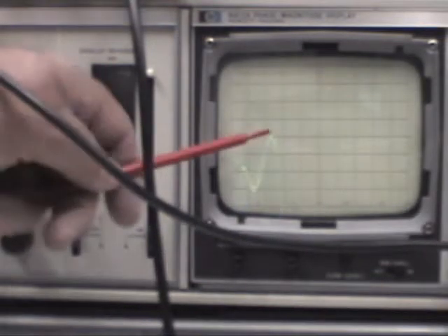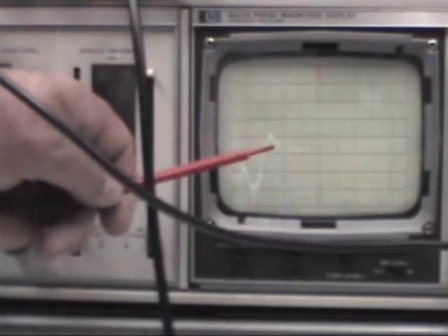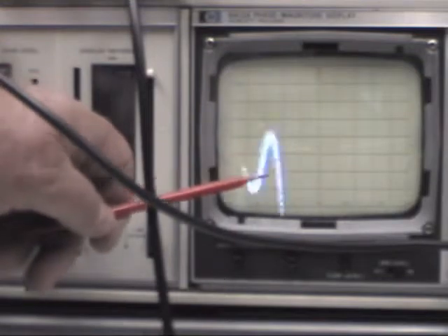And I bring it back down to the center if I can. Which I can't get it right back down to the center. But basically, what we have here is -1 dB right at that point right there. And remember these are 1/4 dB per division, 1/4 dB, 1/2 dB, about 0.75 dB of ripple on the filter.